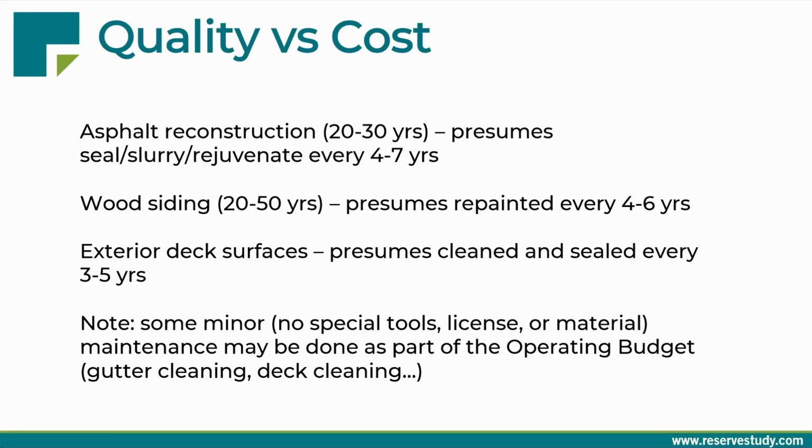The wood siding useful life is based on the presumption that it'll be repainted every 4 to 6 years. Exterior decking, we are assuming that the sealing will be completed, and these will all be additional line items on your reserve study. And also, in some situations, the operating budget will reinforce the reserve planning with the annual maintenance that you aren't handling from reserves.